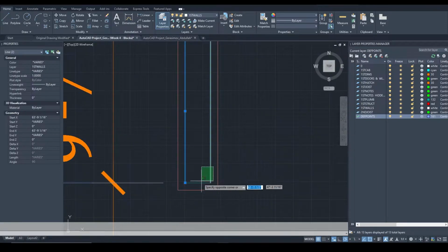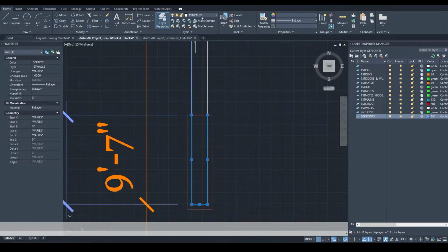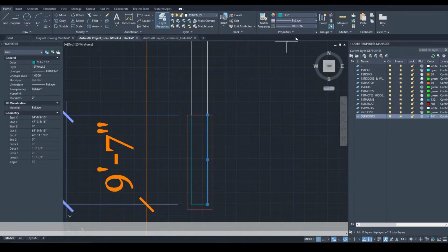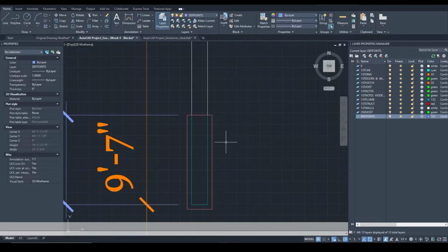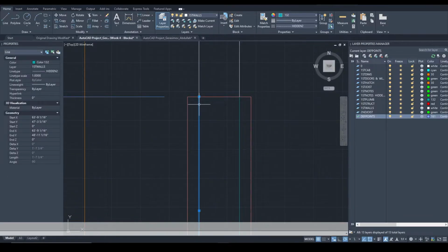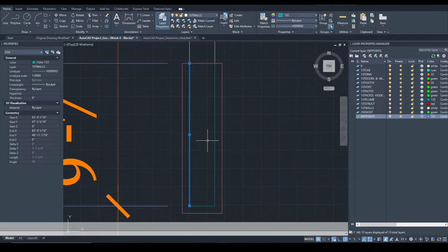So this line and these two lines essentially are going to be created in the same layer, first walls. However, their style will be, as you can see on the left side, color 132 and line type hidden 2. Make sure you specify them. Once you get to this point and you draw these lines, I'll show you the width. You have to offset them 1 inch from the blue lines in order to show the cap.